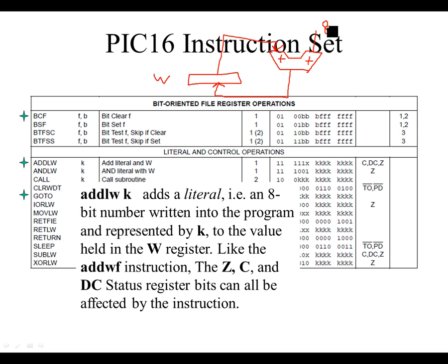So this 8 value has to come from the actual instruction itself. Inside of the instruction, really the instruction is always in what's called the IR, the instruction register. So this value of 8 actually comes from the instruction register, which is these bottom 4 bits.